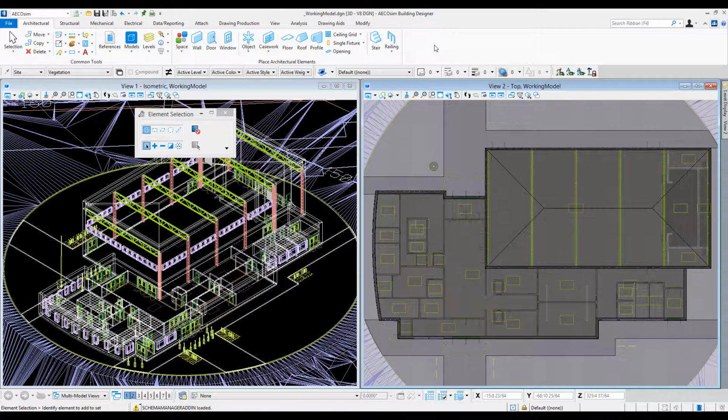In this video, we'll take a look at exporting the design model from EcoSim Building Designer for use in EcoSim Energy Simulator. So this export will take the architectural spaces, the walls with the openings, the windows and door fenestrations, take that into a DGN file that's an analytical model that can be used in Energy Simulator to run our energy simulations.